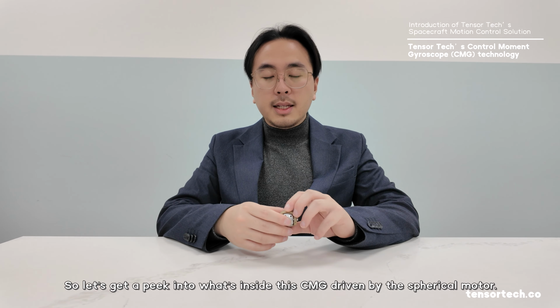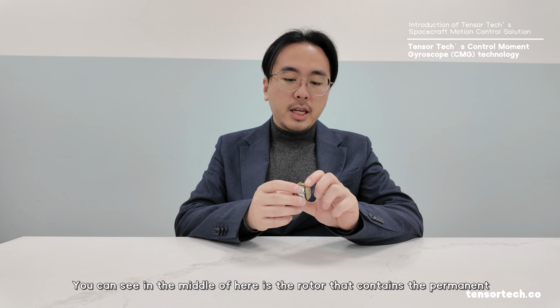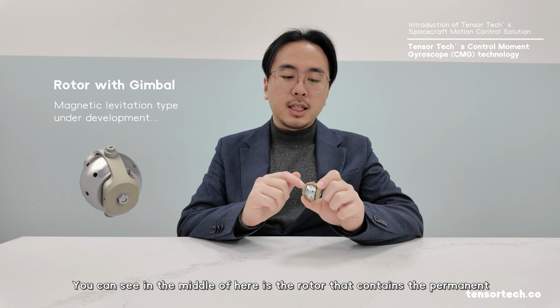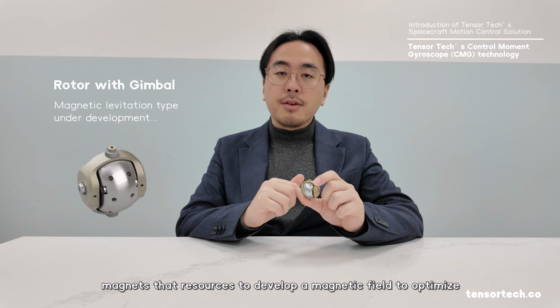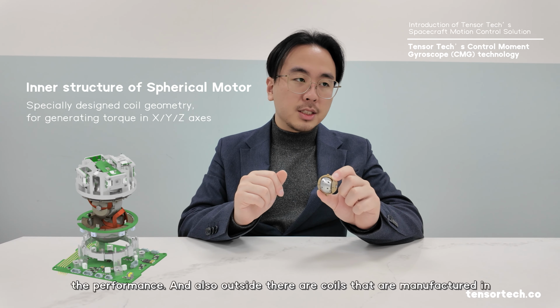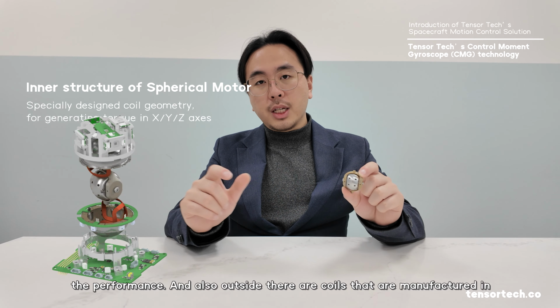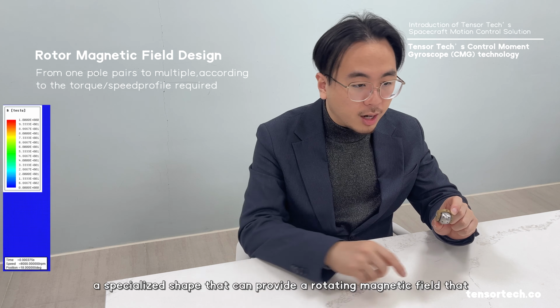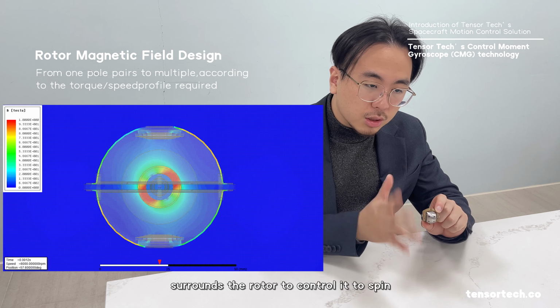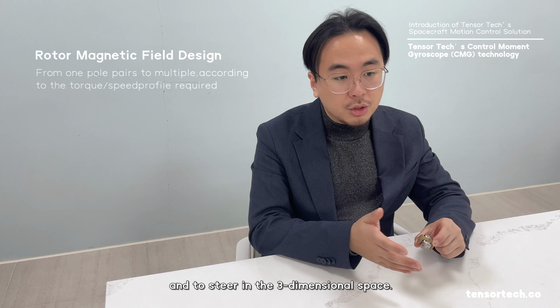So let's get a peek at what's inside these CMGs driven by the spherical motor. You can see in the middle here is the rotor that contains permanent magnets, for which we invested resources to develop the magnetic field to optimize its performance. Outside of that, there are coils manufactured in a specialized shape that can provide a rotating magnetic field surrounding the rotor to control it to spin and to steer in three-dimensional space.